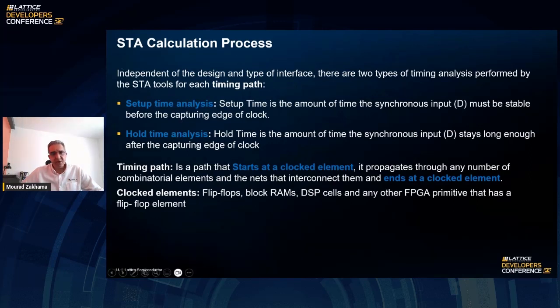The hold time is the amount of time that the synchronous element, the flip-flop, has to have the data stable after the clock, so it does not corrupt the data output or go to a metastability situation. So what is a timing path? The timing path starts at a clocked element. Any path that starts at a clocked element and ends at a clocked element is checked for these two timing analyses, setup time and hold time analysis.